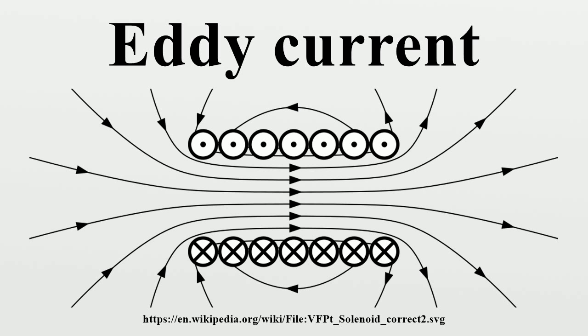Attractive effects. In some geometries, the overall force of eddy currents can be attractive, for example, where the flux lines are past 90 degrees to a surface. The induced currents in a nearby conductor cause a force that pushes a conductor towards an electromagnet.